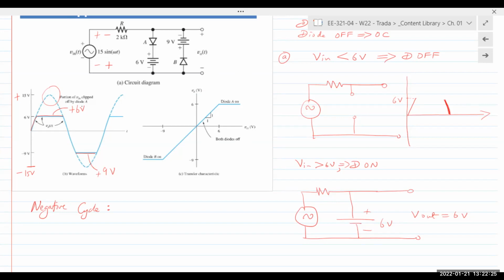Yes. So V out is measured here. So if you imagine a digital multimeter, you're putting the positive reference here and negative here. And the battery has a negative terminal up top. So it sees minus 9 volts. But the operation in both cycles is exactly the same. Positive half cycle, it's diode A. Negative half cycle, it's diode B.